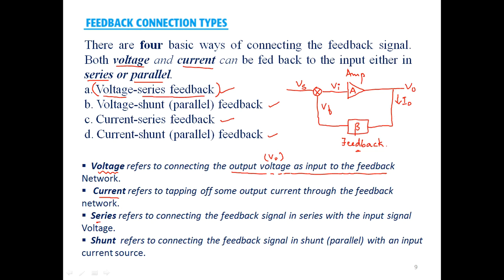Similarly, what does series refer to? Series refers to connecting the feedback signal in series with the input signal. So series means both the input Vs and the feedback signal Vf should be in series, which means I can just add them up, Vs plus Vf.